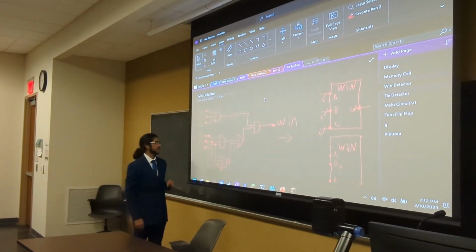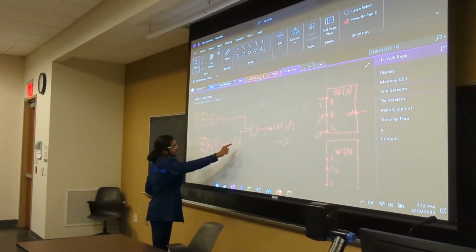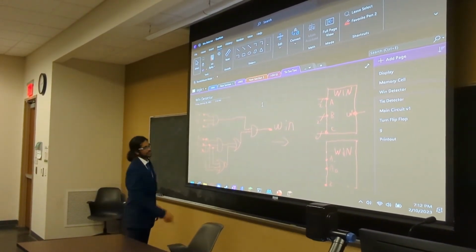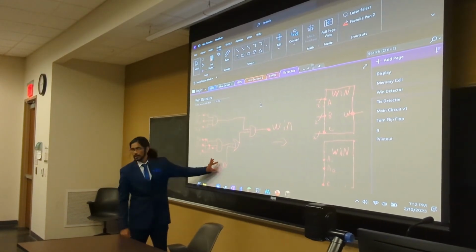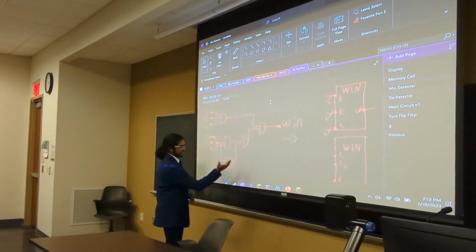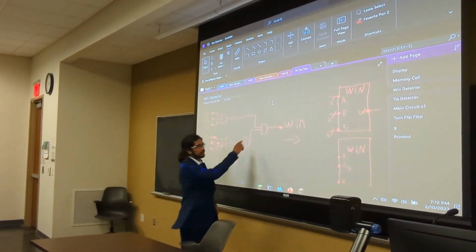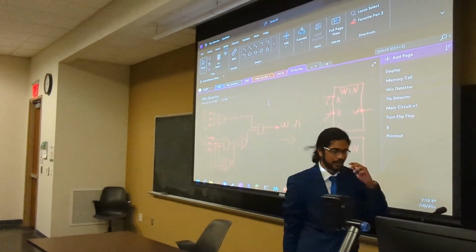And then here, this one says if all 3 of them are X, we want to output a 1. And this one says if all 3 of them are O, because this is an OR gate but inverted, so if any of them turns on, then it'll turn off. And then we send that into the OR gate and into the AND gate, and we get a win.